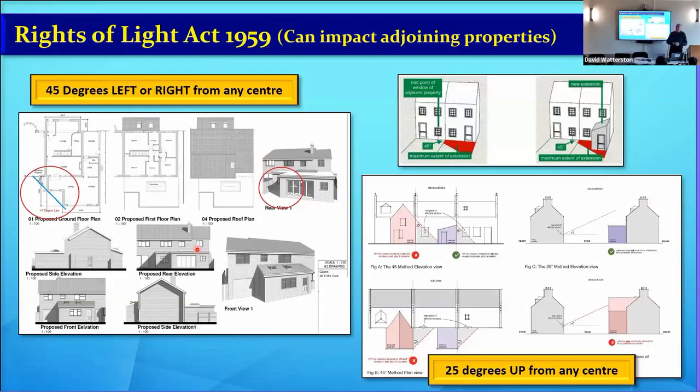And rights of light. I don't know if anybody's come across rights of light. This is exactly the same. You cannot build anything, a nice gazebo, plant mature trees, have a line of cypresses or whatever your client wants, that cuts out the light from your neighbour. They've got a right of light. I used to think it was from the nearest reveal, but it's not. It's from the centre of the window or door. They're allowed 45 degrees of light either side.